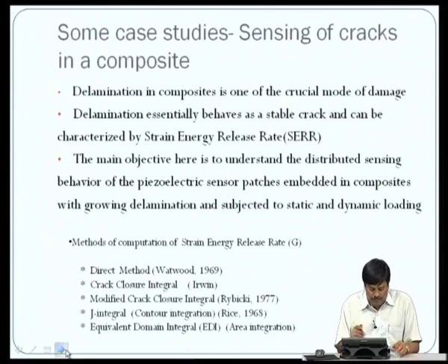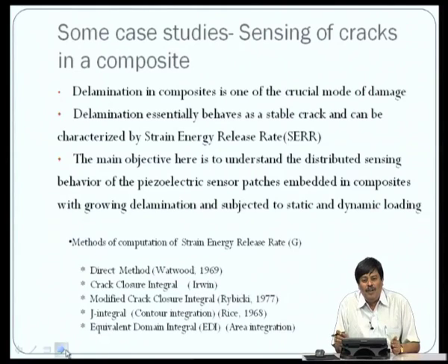Now let us do some case studies using the formulated element. Here we show how the piezoelectric material can be used as a sensor. What we did before is the actuation problem, where we made the deflection 0, but here we see how we can sense the presence of a crack.